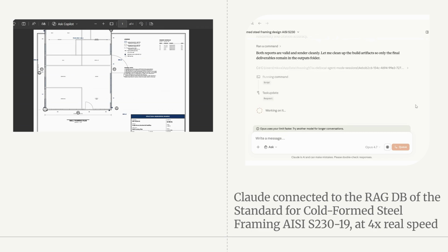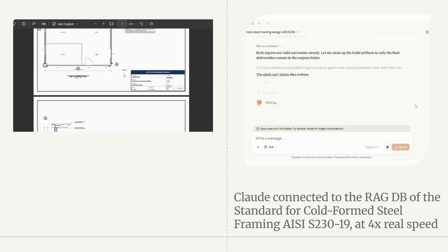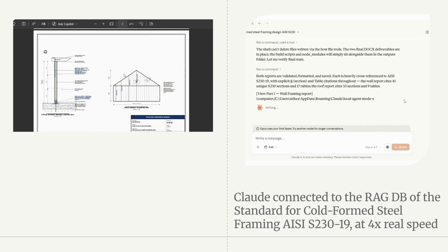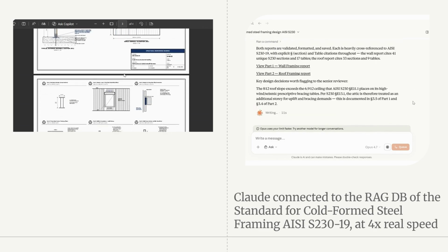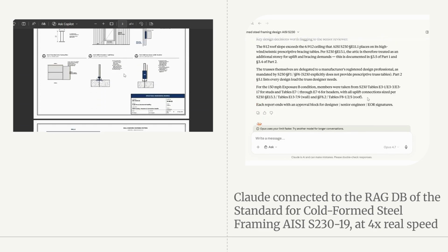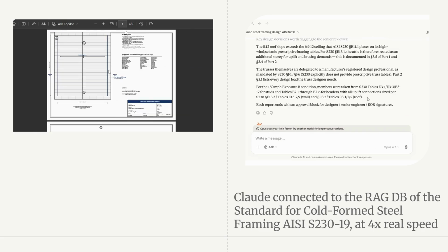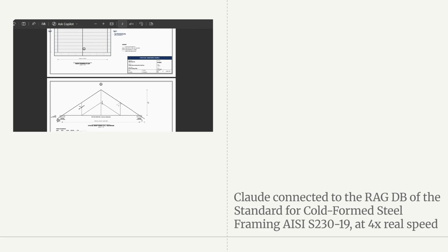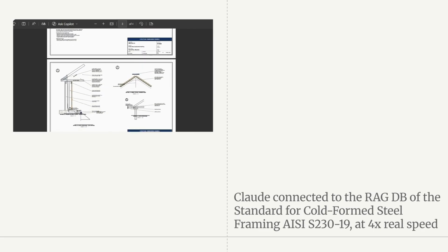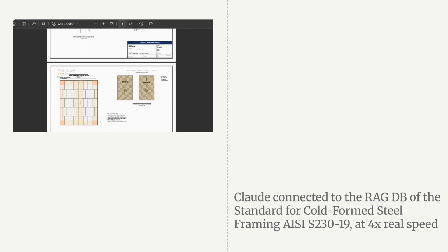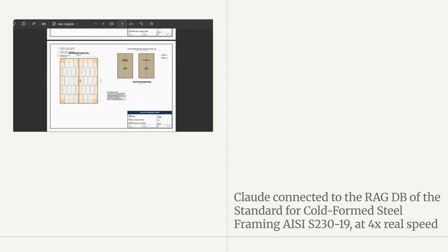The drawings provide wall plans with framing details, wall elevations with strapping detailing, gable end wall design, detailing for openings, corners and anchoring, and sheathing and fastening details for the shear walls and ceiling and roof diaphragms. And finally, the roof drawings provide the roof framing plan, indicative truss elevations, strapping details, ceiling and roof diaphragm details, and the roof sheathing layout.